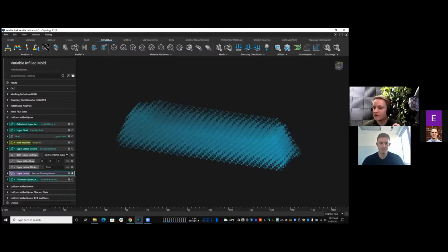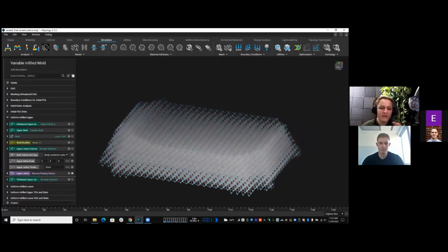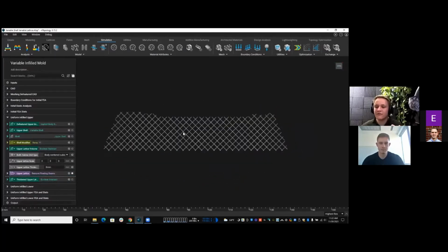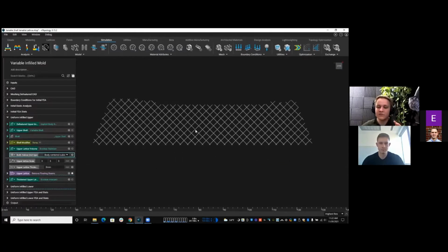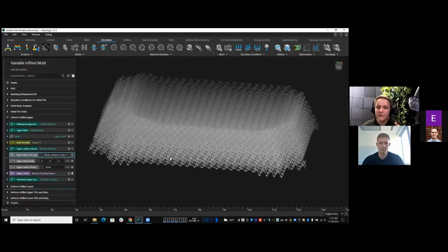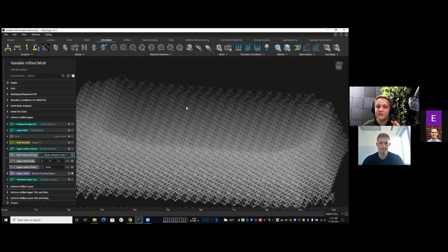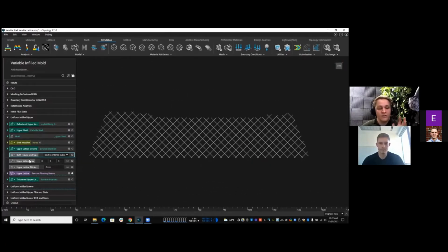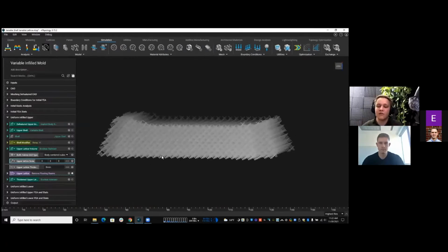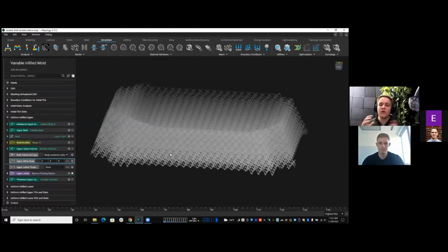Right. So let's focus on just the lattice structure for a second. I'm going to choose a couple of things. The first thing I need to choose is the unit cell, right? And I chose this body-centered cubic, in conjunction with Fortify. We like this because of its completely self-supporting nature, right? There's nothing below a 45-degree overhang, so it's completely self-supporting. I chose the unit cell size of 3 millimeters square, and the reason for that is the unsupported overhangs, right? That's the largest unit cell we could do to make sure this part is completely printable without any added supports. We didn't want to mess with that at all, so we chose 3 millimeters.